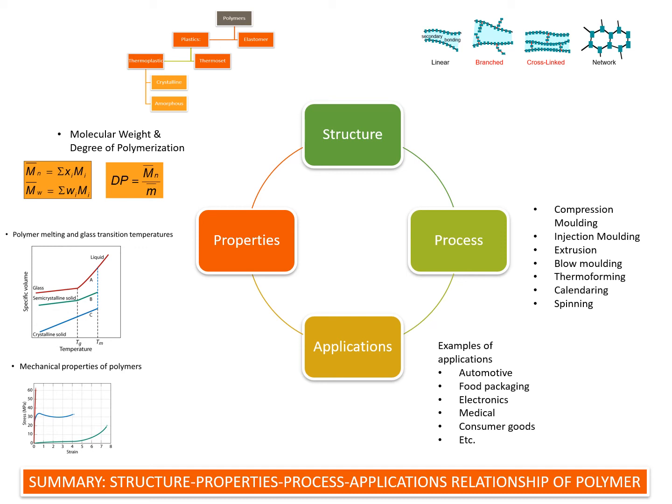We have also discussed the mechanical properties of polymers. We know that thermoset materials are the stiffest and also the most brittle type. The thermoplastic materials are more ductile and have average or moderate strength, whereas the elastomer material, which can expand greater than 200%, is very weak in terms of mechanical strength, but has a lot of ductility.